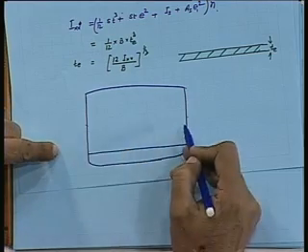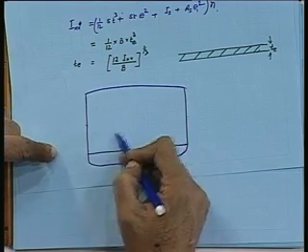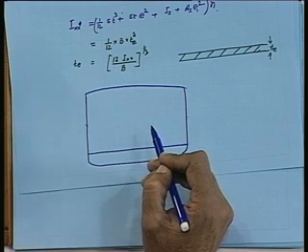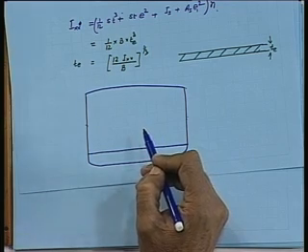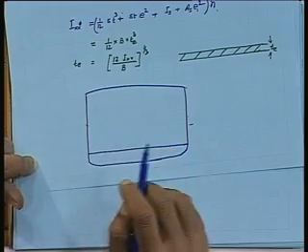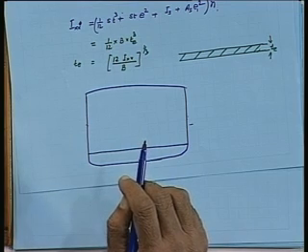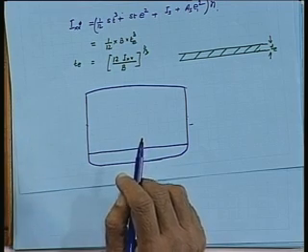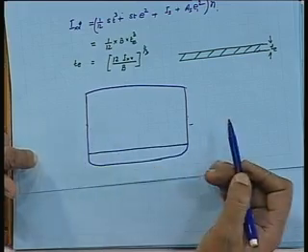So, the bending stress at the same location for a horizontal stiffener will be 4 times, or the bending moment will be 4 times more than the vertical one. And therefore, to counteract the stresses, if the permissible stress limit is the same, you require 4 times the section modulus compared to the vertical one. But the next question will be that you will have fewer horizontal stiffeners, and therefore the weight may not increase. Weight will definitely increase because the span is increasing here.